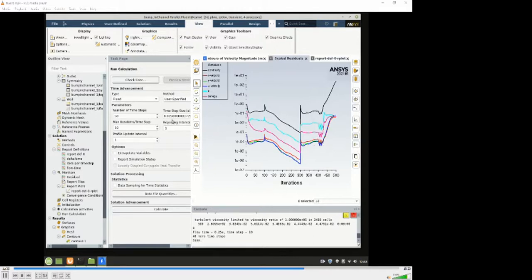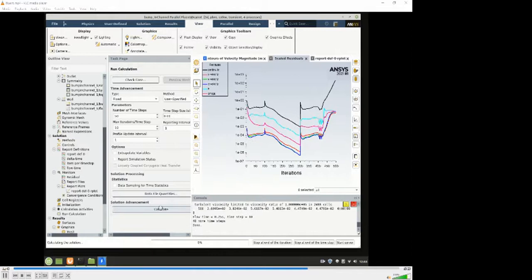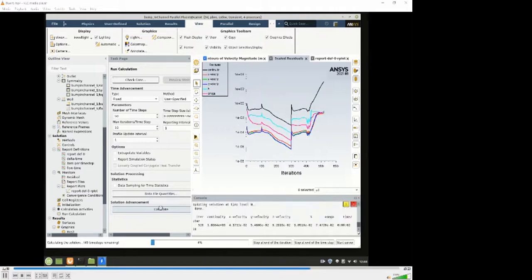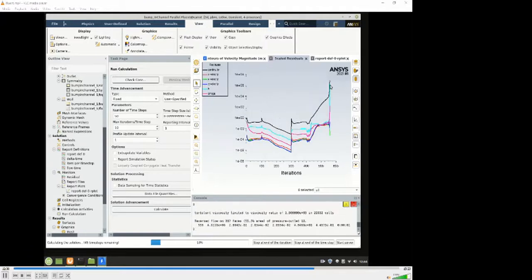You can go and calculate what the appropriate time step should be, but we can just bring it down a little bit and work from there. In fact, there's every indication that the continuity equation is diverging. So this is typically what happens with a CFD calculation if you try to do something which is non-physical.